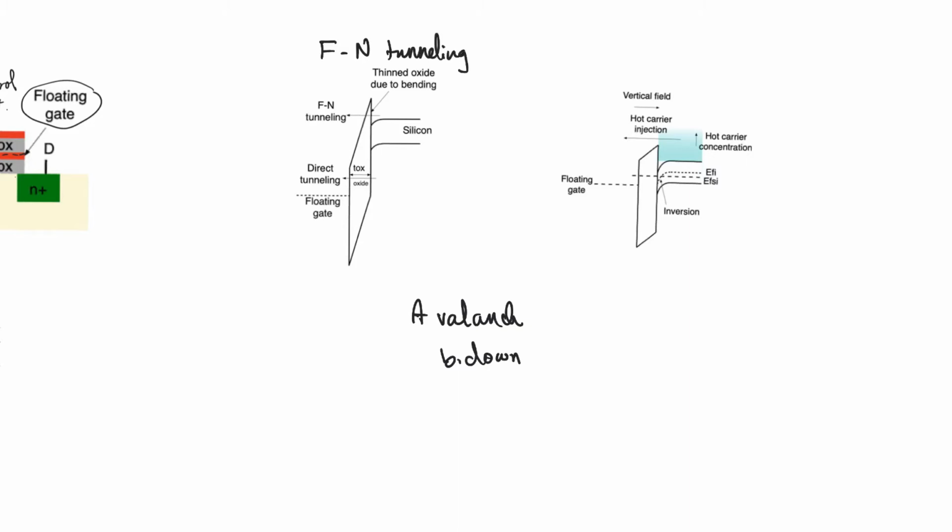And this is a kind of tunneling, but it is not similar to the direct tunneling we discussed in Module 10. It's related, but it's a little bit different. And the third is the hot carrier effect, which we discussed in detail in Module 10, and specifically here we call it hot carrier injection, because it's not just a side effect or a secondary effect that we observe, it is something that we are doing intentionally and trying to benefit from.